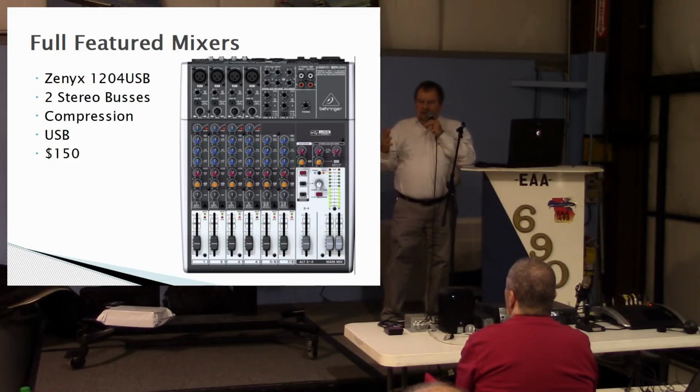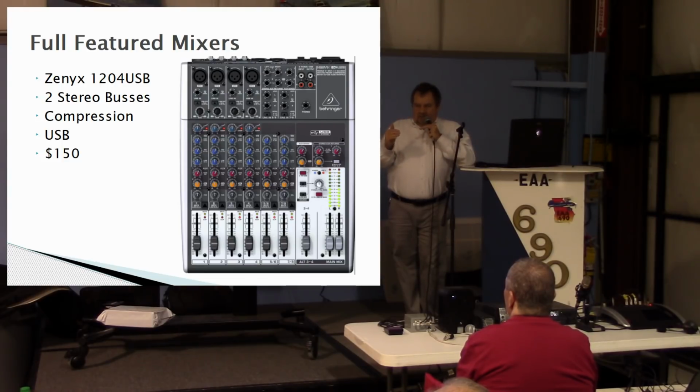Why do we want to do that? It seems like you're reducing your audio output. Well, you are. Overall, you're reducing your audio output. You're compressing it into a tighter band. And then you crank the gain up. And it comes back up to full gain, so you're just barely deflecting ALC on a single sideband. But overall, RMS-wise, average power output is increased.